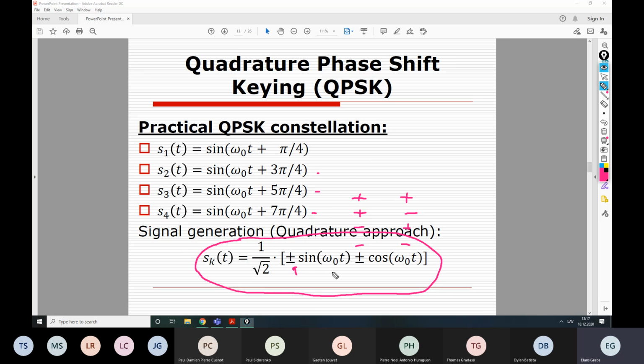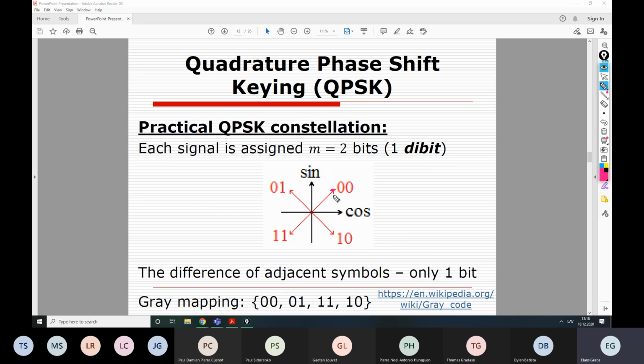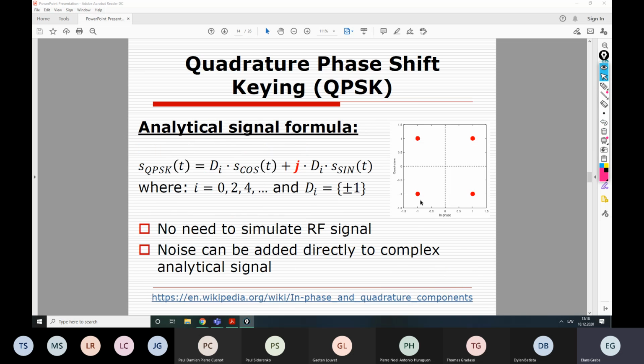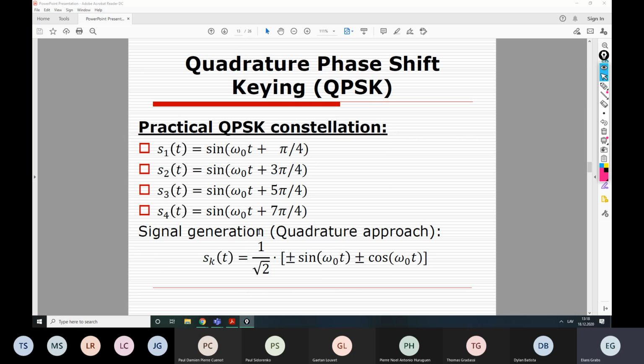And here, plus and minus is just a multiplication with +1 or -1, which are NRZ levels, right? And this way we have these 4 different signals with π/4 initial phase shift, which represents this point. Here is π/4. Next one would be 3π/4 here, then here, and lastly here, right? So that's how we generate these signals. And that's because we actually can generate them with the same generator, which generates at some specific frequency omega 0, or 2πf0 in linear scale.